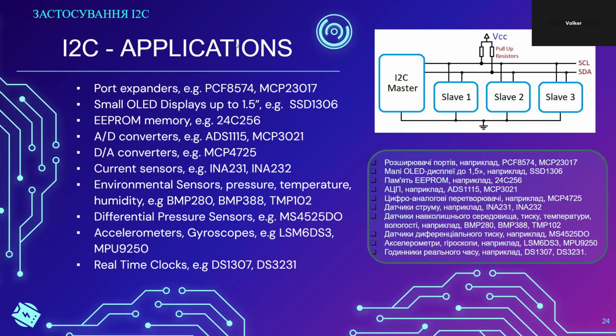With the I2C interface, it would take a long time to read out the data. The SPI interface is much faster. These serially interfaced NOR flash chips have an SPI interface and not an I2C interface because of the slower speed of the I2C interface.